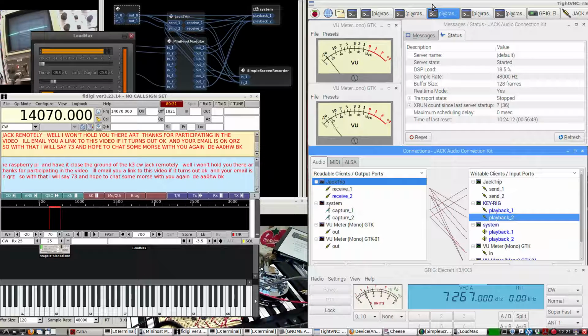You have to have JACK audio for this to work efficiently like this. I'm using 48K, 128 frames. We have some XRuns, but not too bad since we're taxing it fairly well. The VU meter is what's coming to the input from me, from my remote computer. As you see, this needle is bouncing back and forth.